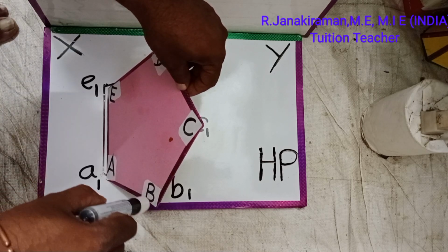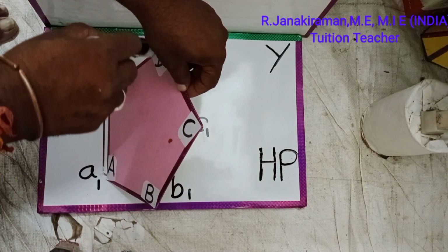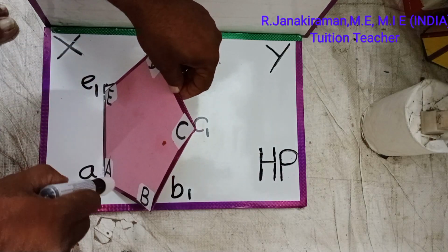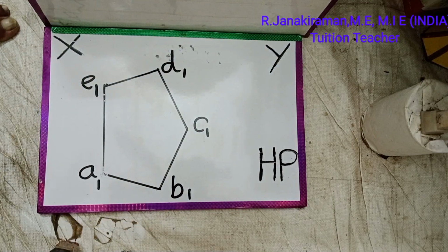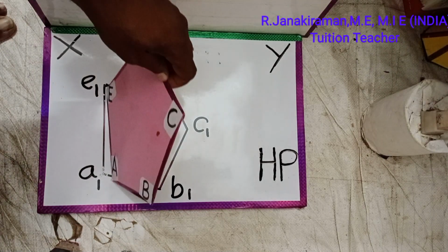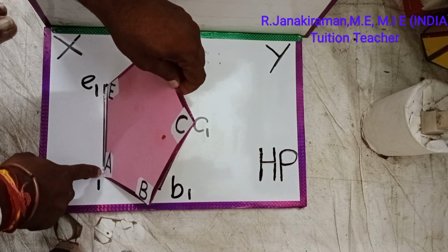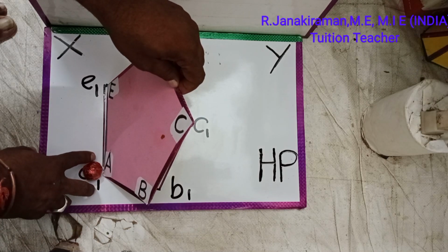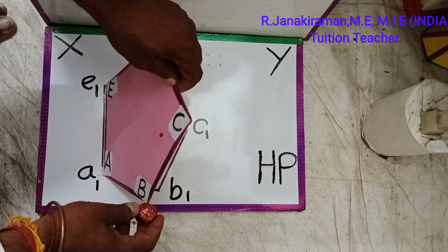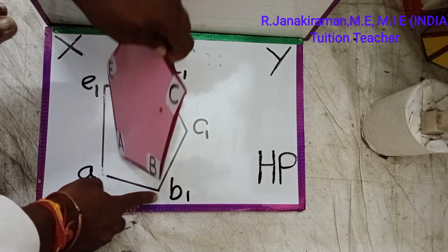This pentagon is smaller in size. You can see the rose color portion will be smaller in size. It will be our fourth diagram. This is the diagram, called surface inclination top view. It is obtained like this. Point A, having contact on the horizontal plane, is projected on A itself, on the HP itself. Similarly, B is projected on the horizontal plane, marked as B suffix 1.